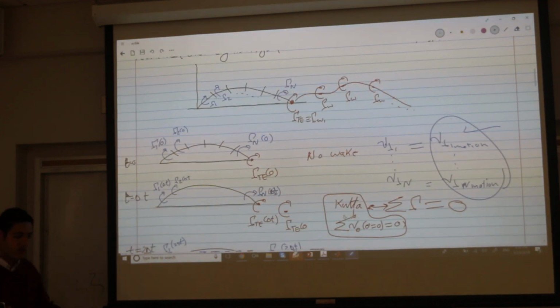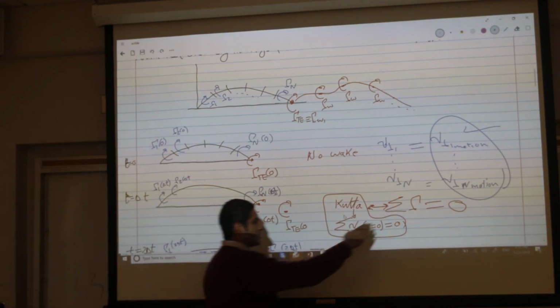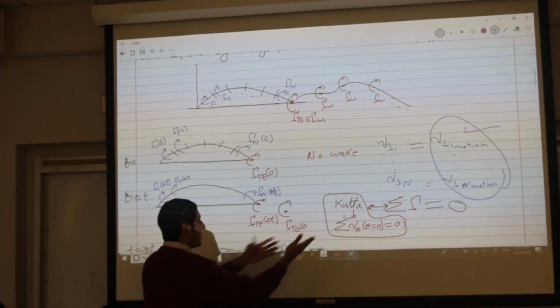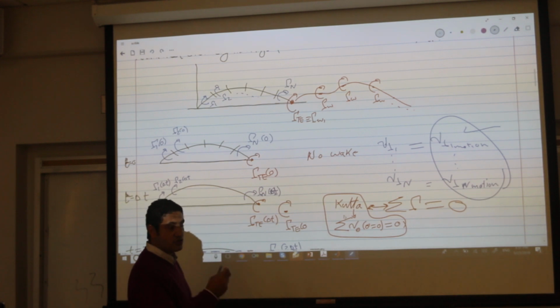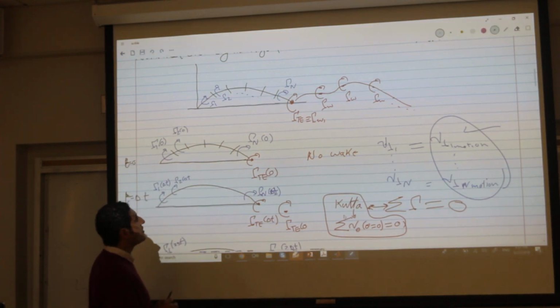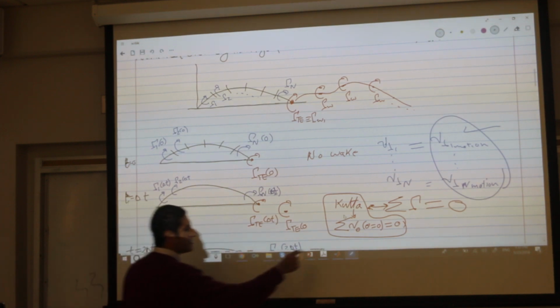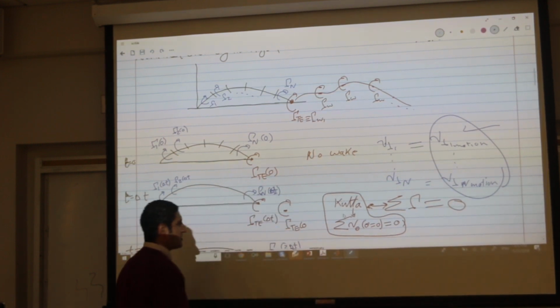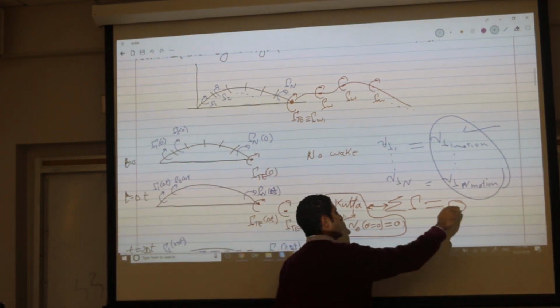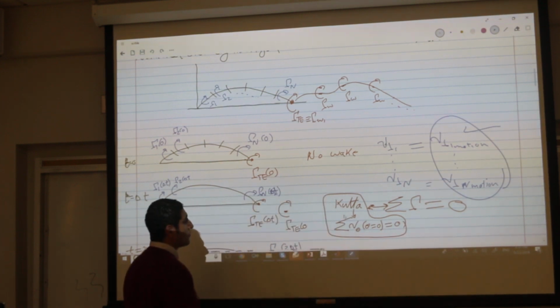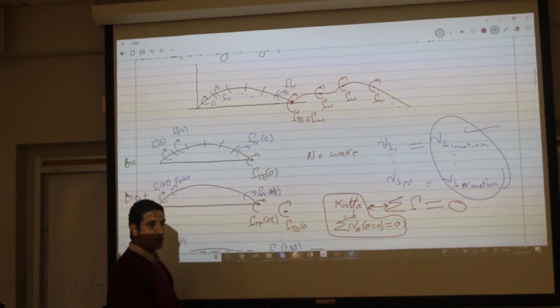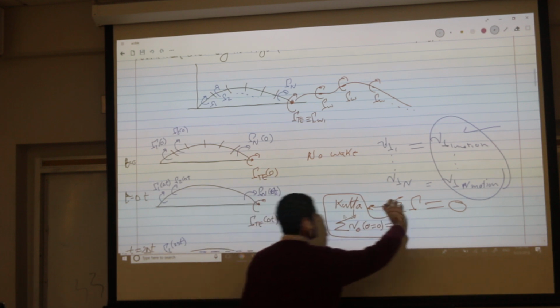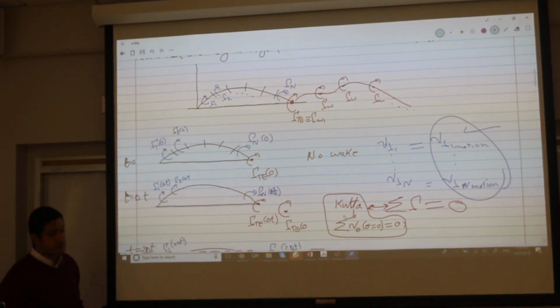As you saw in the theoretical formulations, this extra equation depends on how you formulate the problem. For Theodorsen, the main governing equation was the Kutta condition. For von Karman and Sears, the main governing equation was the law of zero total circulation. For this formulation, we have no means to apply the Kutta condition actually. If you want to apply the Kutta condition at the sharp edge explicitly, you need to do it in the cylinder domain and ask that the tangential velocity vanish there. If you do it like here, it's much easier to do the law of zero total circulation. So we will do it with the law of zero total circulation, and one of the projects, I guess, Fabian selected. So you will just need to replace the last equation with something else coming from your formulation.